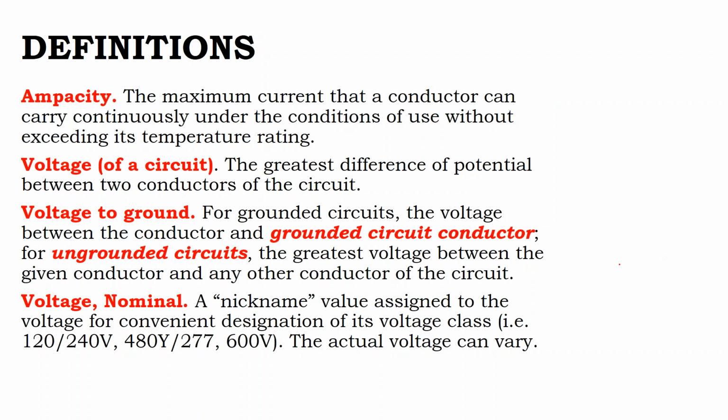Either you didn't do the 75C calculation for that disconnect, and that terminal on the disconnect is heating up, and that's causing your cable to smolder, or you messed up the temperature calculation in the cable itself at 90C. Maybe you undersized your cable, didn't allow for derating inside of conduit or something like that.